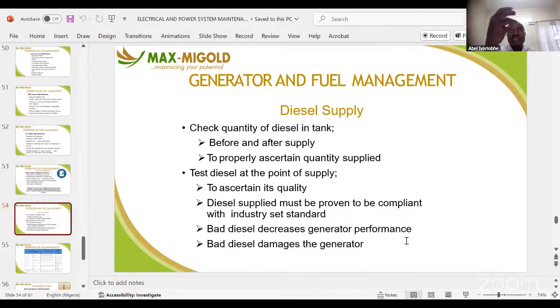The primary water separator is beside your tank. So you have to ensure that the element inside the cup is replaced at regular interval. And you have other small ones before the main fuel filter. So how come your injector is going bad?